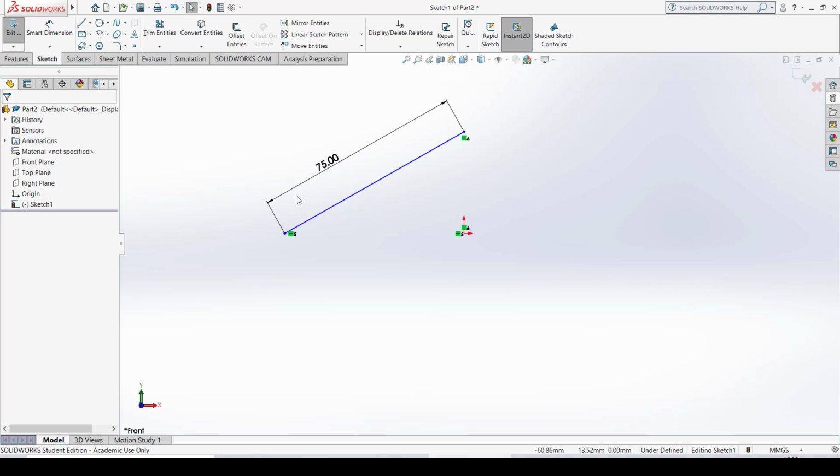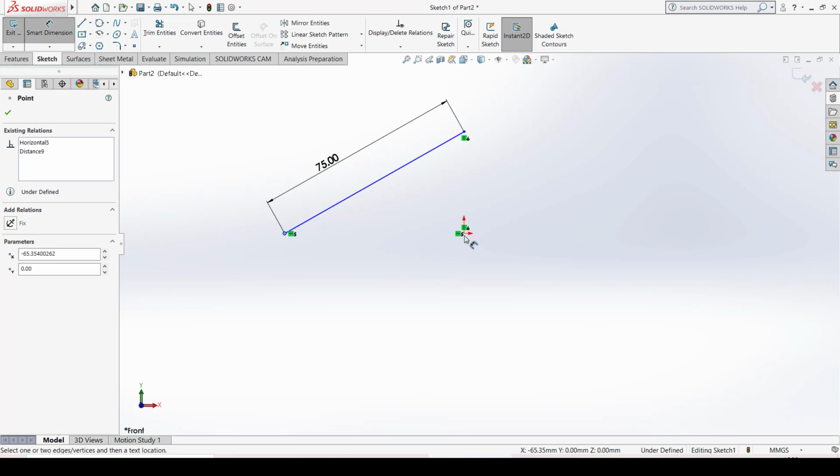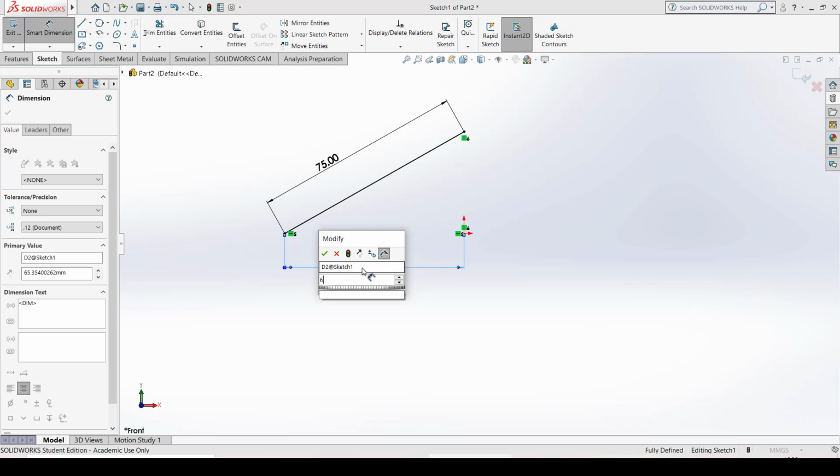Now the first thing you did is provide the geometrical constraint to the system. You make sure that your origin and that point become horizontal. You make sure that your origin and the second point of the line become vertical. Now I want to give a dimensional constraint to it. So give some dimension from this point to the origin. Let us say it should be 60.